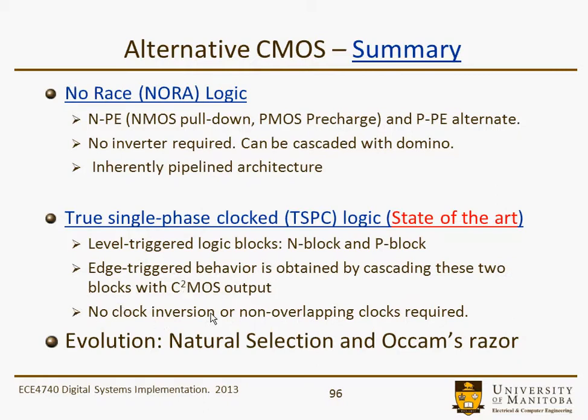And the main point was no clock inversion and/or non-overlapping clocks required. So it's a bit like evolution. We sort of saw some fairly complicated dynamic structures, and then at the end we came down to the one that just had a single-phase clock.